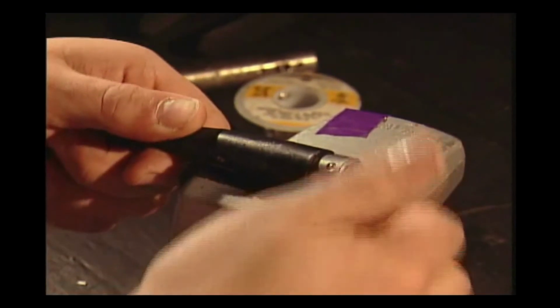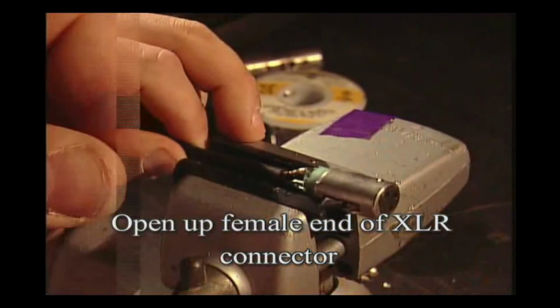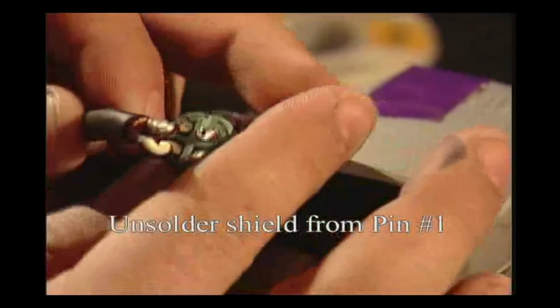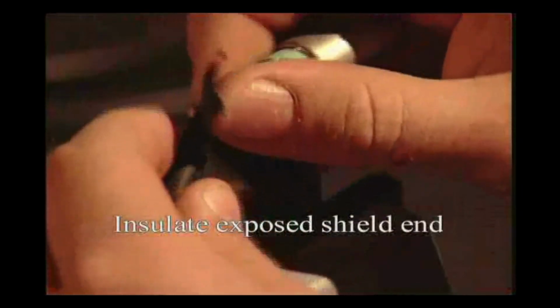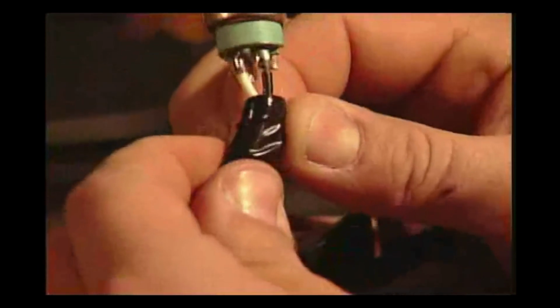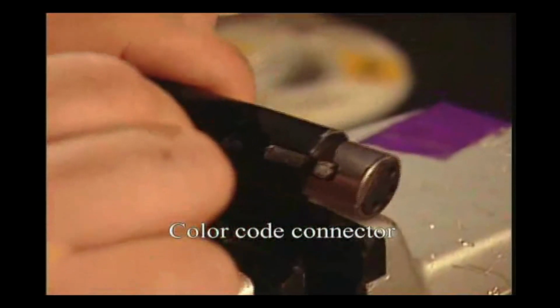Here's how to lift an XLR on a balanced cable. On the female XLR end of a balanced cable, open up the connector and unsolder the shield from pin number 1. Insulate the exposed shield end with electrician's tape to ensure contact is not accidentally made within the connector. After reassembling the connector, be sure to color code it to show it's a modified cable.